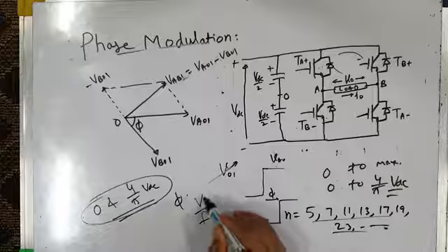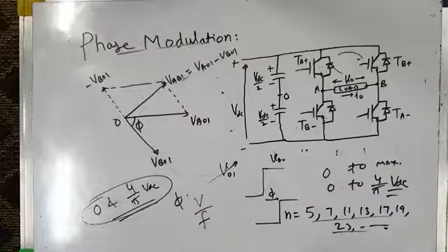By controlling frequency and voltage, we'll be able to control the speed of the induction motor, and simultaneously we will be fulfilling the other objective, which may be minimization of weighted THD or minimization of pulsating torque, etc. Okay, so therefore all these selective harmonic elimination techniques which we have studied are offline techniques. The switching angles are calculated offline and stored in the form of a lookup table, and then they are fetched while controlling the load.